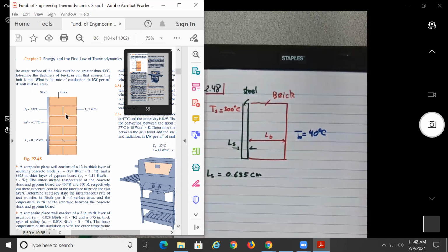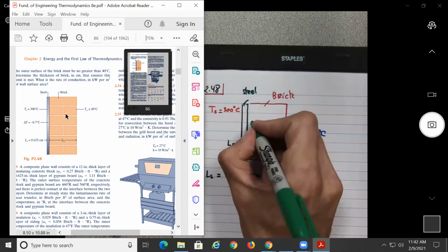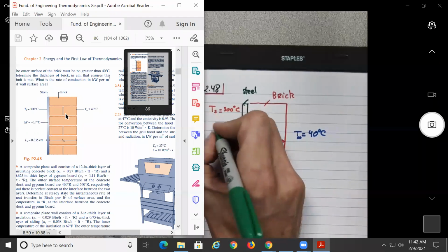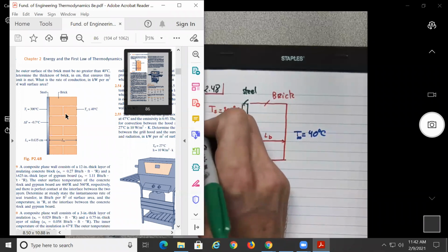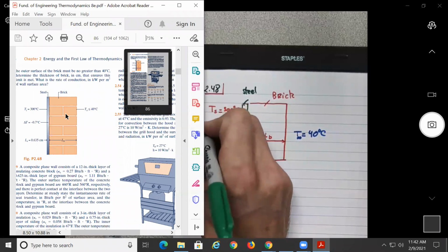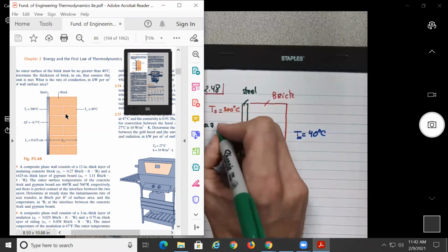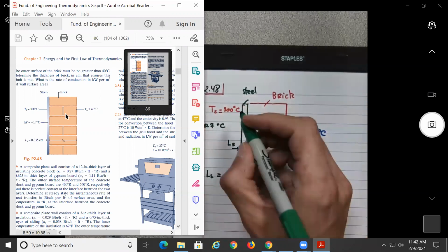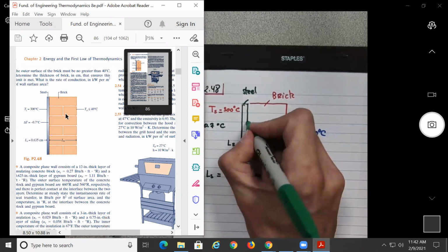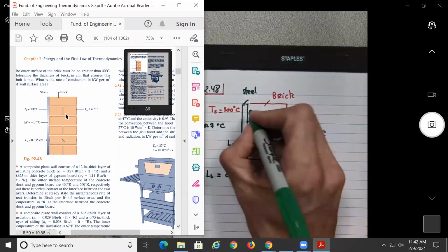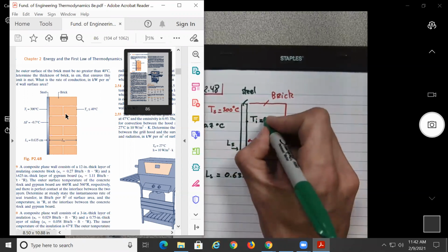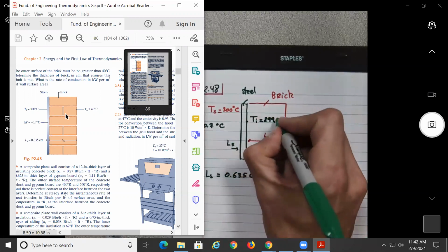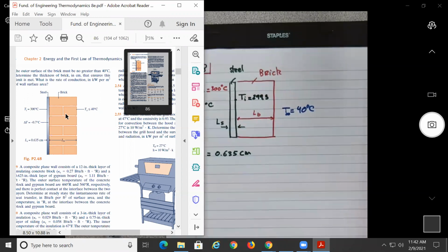And it looks like the temperature difference between the inside and the outside of the steel, so delta T, is negative 0.7 Celsius. I don't know which one I'm going to use, but this will mean what? That the temperature inside, so let's say here T sub I inside the steel, should be equal to what? To 99.3, no? Okay.